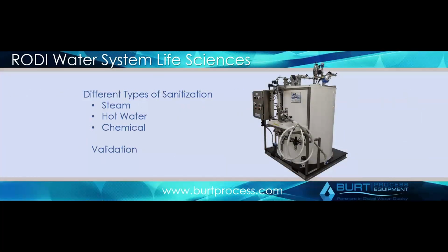In addition to that, they also need to be sanitized, as we talked about earlier, very frequently. Sanitization of these is generally done with either steam or hot water as opposed to chemical, and they're all generally stainless steel. You can see here the thermoplastic tank being fed by all sanitary stainless steel in that regard.